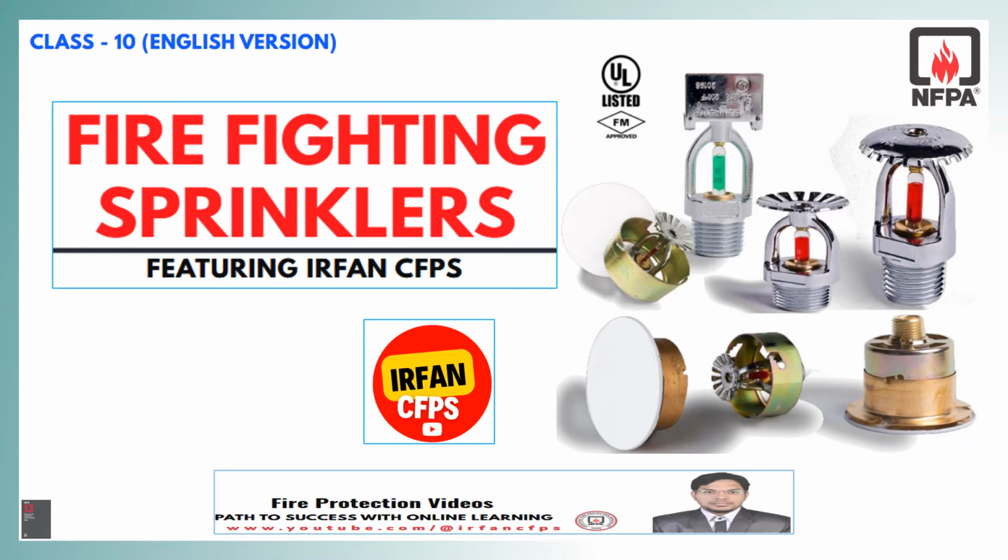In today's class, we shall go through different types of sprinklers used in firefighting systems as per NFPA 13. Please note that there are several different models, finishes and temperature ratings for sprinklers which are used to meet design requirements. These sprinklers come in brass construction with chrome coating, natural brass finish or custom color finish. There are sprinkler models suitable for specific requirements and hazards. Sprinklers shall be UL listed and FM approved as per NFPA 13.